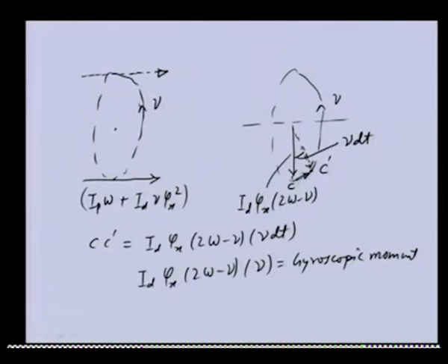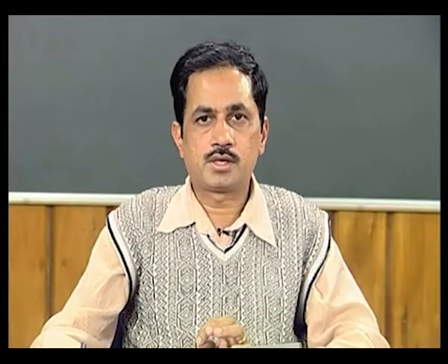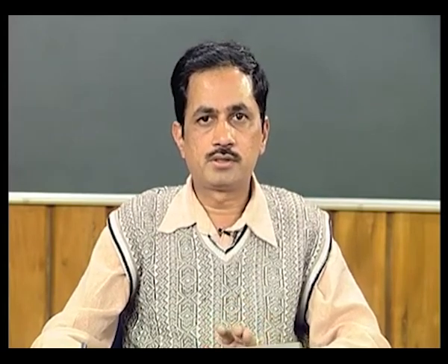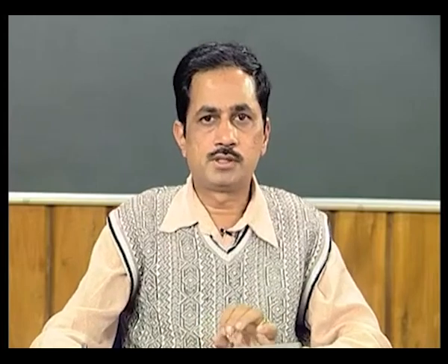So this particular gyroscopic couple which we obtained is the active couple which this disc will experience, and as we obtained, the direction of the gyroscopic moment is from C to C prime, that means into the screen.